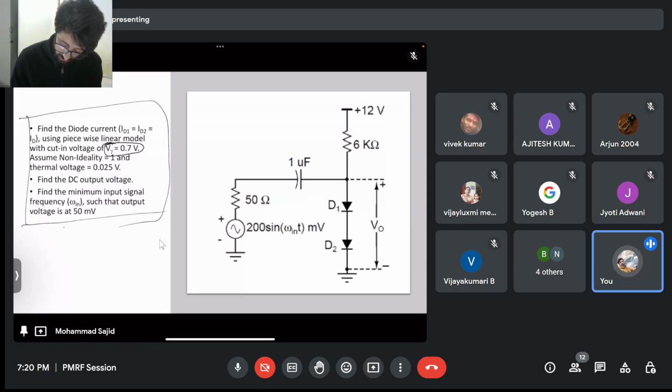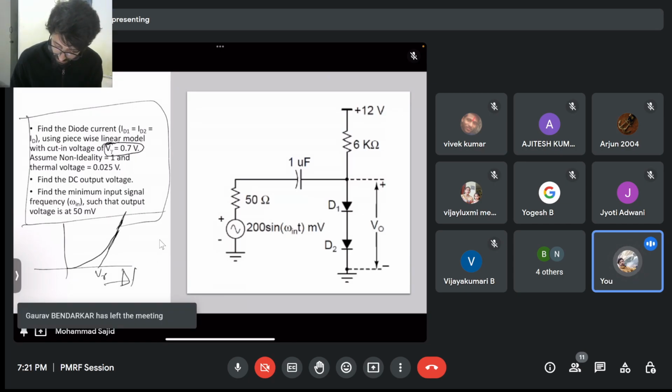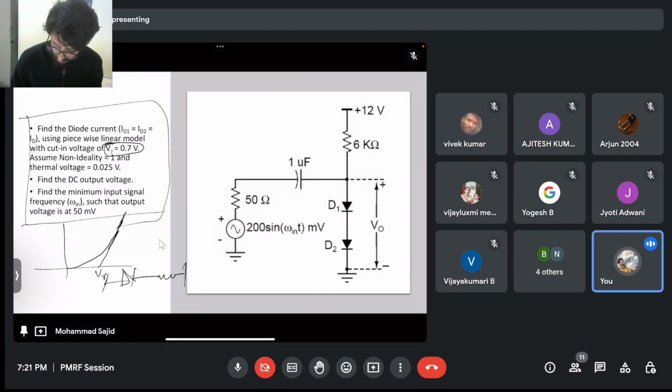Just for the diode characteristics, you know that this is the cut-in voltage, but a diode always has a resistance connected with it, right? So for the diode, you cannot apply a voltage greater than its built-in voltage. Whatever voltage you increase, the current will increase, no doubt, but the extra voltage will drop across the parasitic resistors, or some resistor you have connected in series.